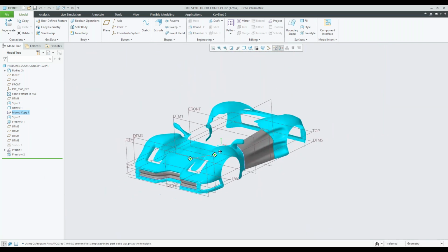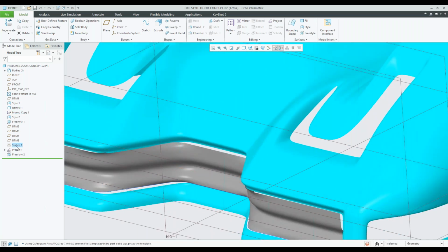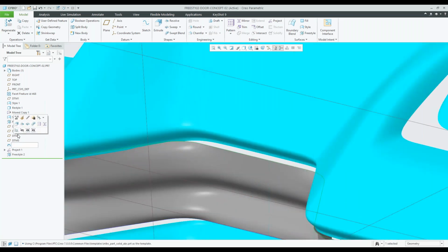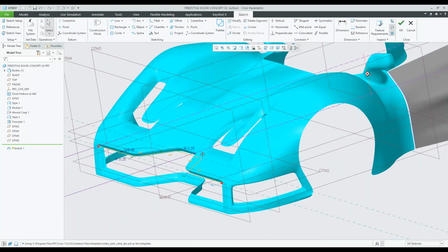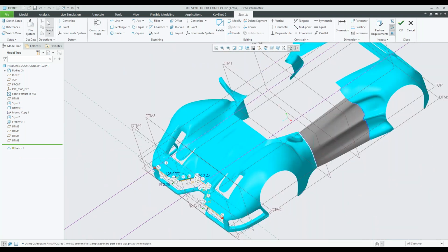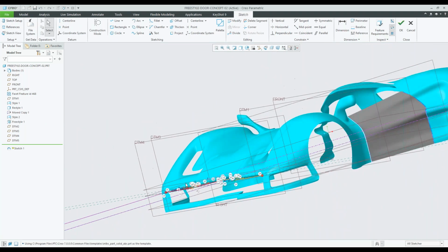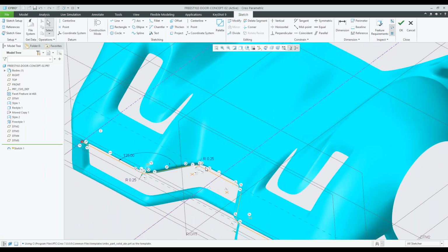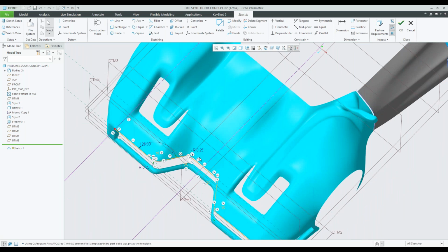So one more thing I wanted to show is that, aside from the style curve, you can link a freestyle mesh to just a normal sketch curve. So we have Sketch 1 here. Let's unhide that. All right. So we can see we go back into Sketch 1, Edit Definition on that. I had these different planes, a Datum 4 and a Datum 3 plane created, and this plane down here as well. And I use these two planes up here to dimension this sketch, right?